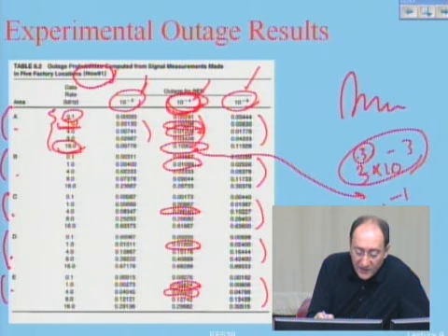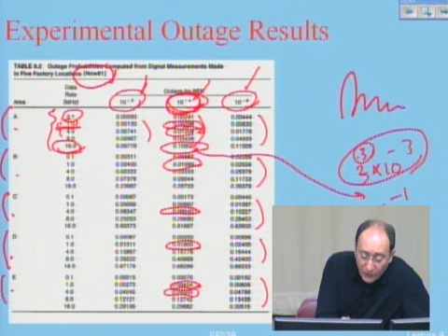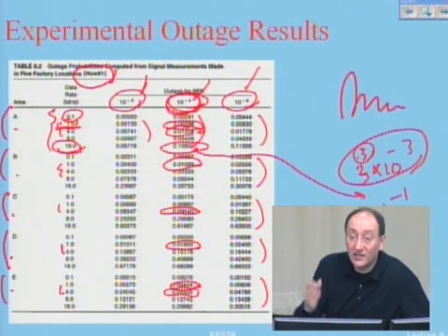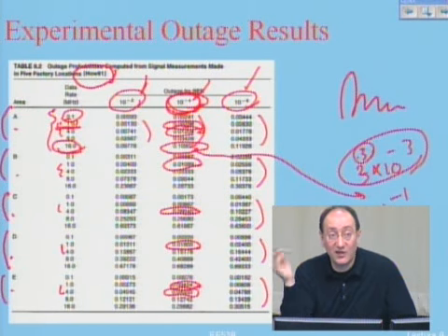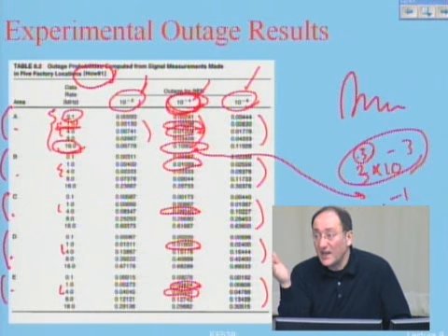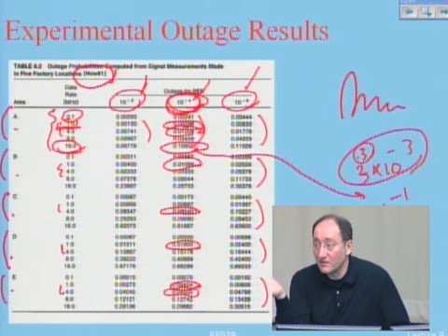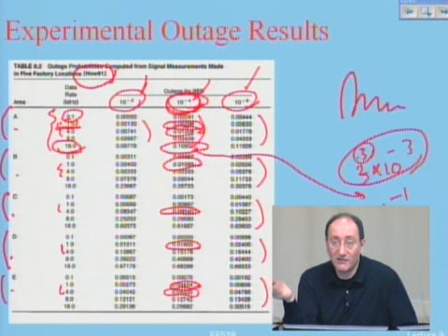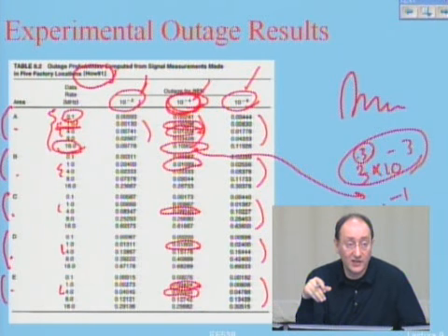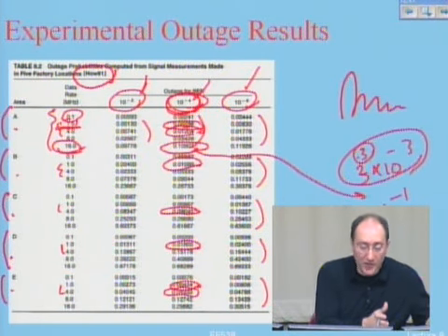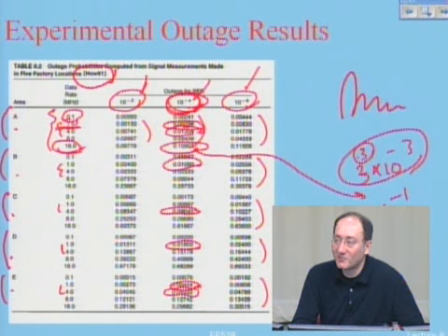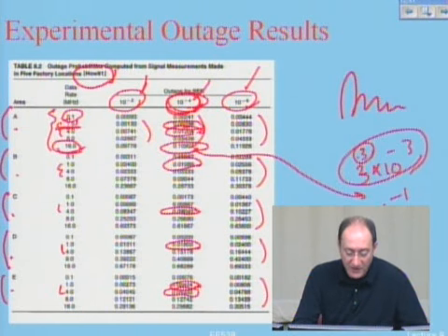I look at all of these guys, I see that the data rates between 1 to 4 megabit per second provide an outage rate of around 1%. A 1% outage rate is acceptable because 99% of the locations I have good signal. In that 1% I don't have good coverage, and I can possibly move my laptop a little bit. But it depends on what you want to say.